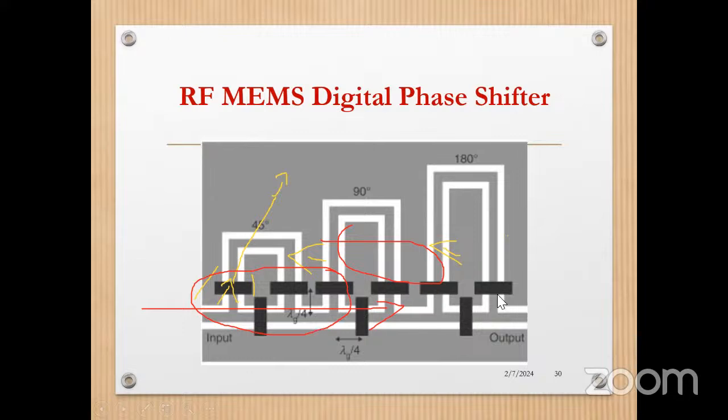and another output will be a 180-degree phase change. So wherever a modulator is there, we need a sine signal and a cosine signal. I cannot use two different signal generators for generating a sine and cosine because a signal generator is too costly, too expensive to implement. So if an electronic device has more signal generators, it will become costlier. Right.